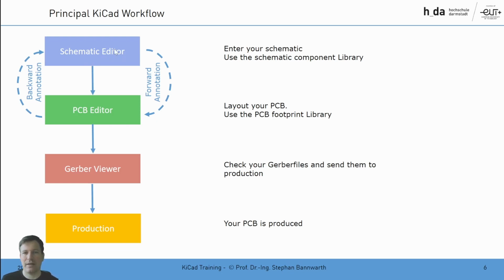You change the footprint in the schematic, and then you say update my PCB, and you can still use the so far layouted PCB, but one footprint changes. And the same is when you design your layout and you say, oh, I want to change the device and I need another footprint, then maybe the pin numbering is changing, and then you have to update your schematic. So this means with the dashed arrows, this is a more or less iterative process.